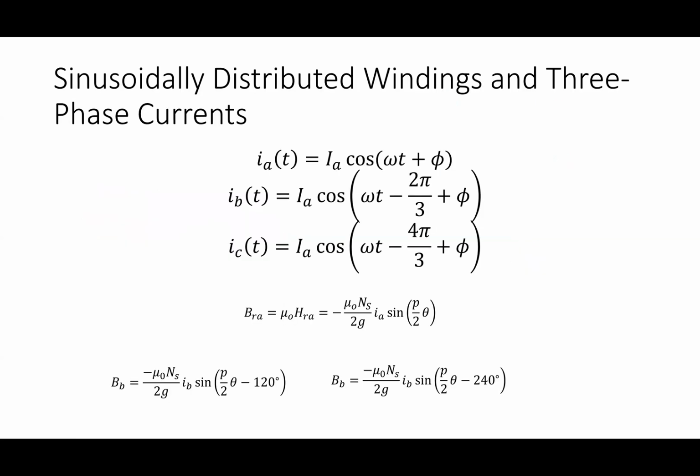All right, so let's look at what that means. This is what we've kind of determined up till now. If I have this machine, my stator currents look like this. Okay, so I want to go back and remember for a second. If I turn this into the phasor domain, how do I write these? The first one is I angle here. I'm going to say IA over square root of 2 to get it to RMS, and this guy has an angle of 0 degrees. And then these guys would all be similar. IB is the same magnitude with an angle of negative 120.